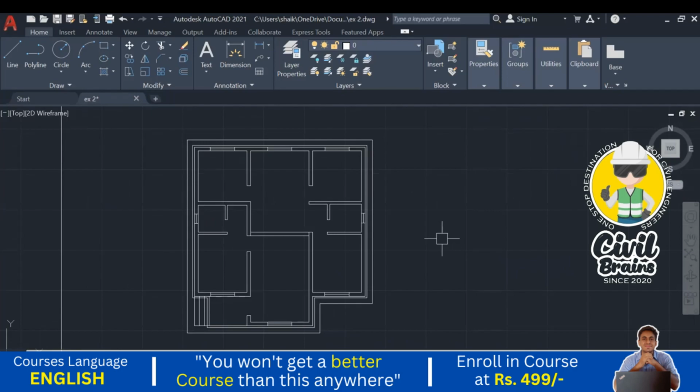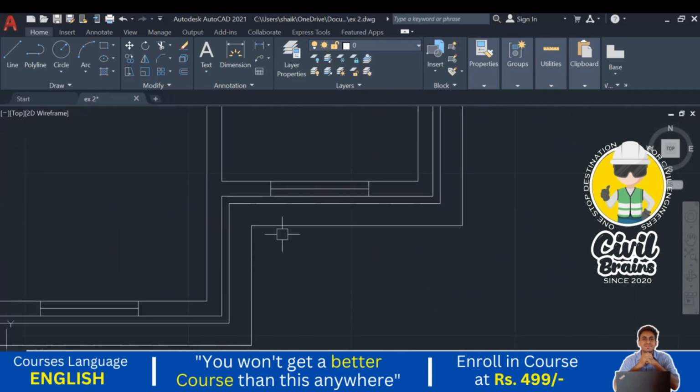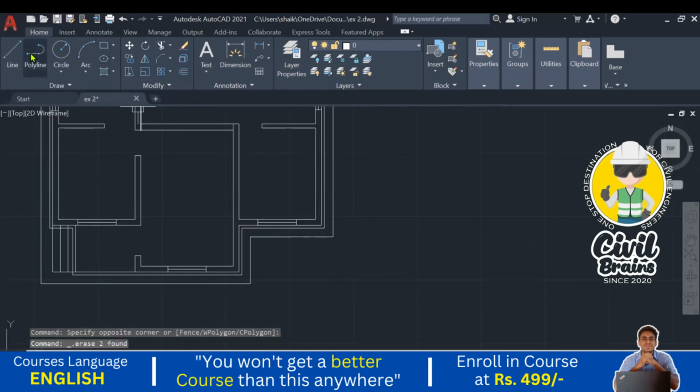Okay, so next we need to show the Chhajja projection. Chhajja projection we need to show at the windows. What is the Chhajja projection? Chhajja projection is 0.6 meter. I just draw the Chhajja first here. Width of the window is how much? 1.5 meter, and Chhajja is 0.6. Okay, I will tell you one more time how to draw the Chhajja.